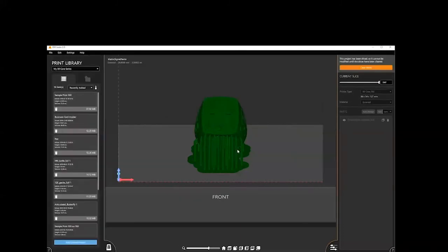Once it's done, you'll see that this window on the right has now changed. Now you have the option of clearing your slices. The only time that you'll need to do that is if you saw, as the model was growing, a completely missed spot that you didn't support, and you're like, oh, I need to go back and support that. You can't do that unless you hit clear slices.